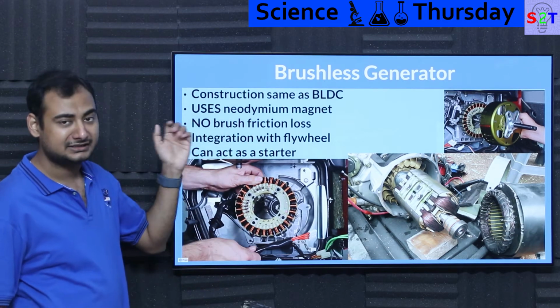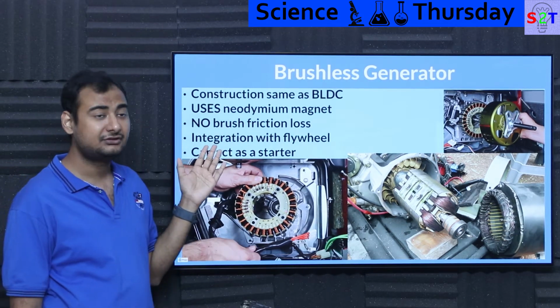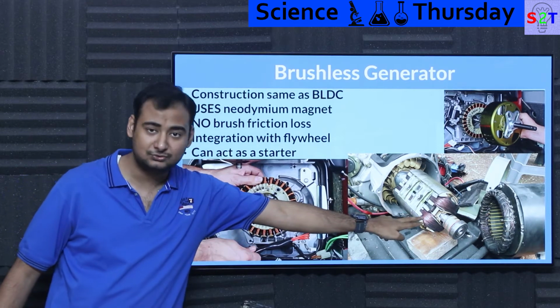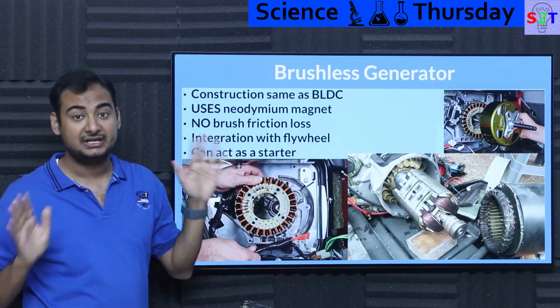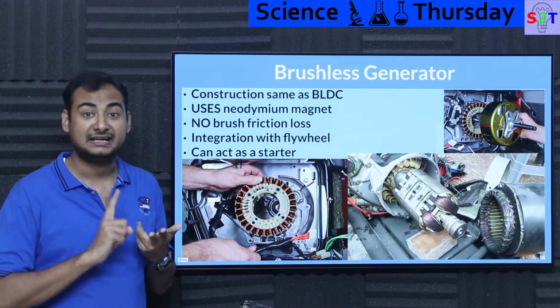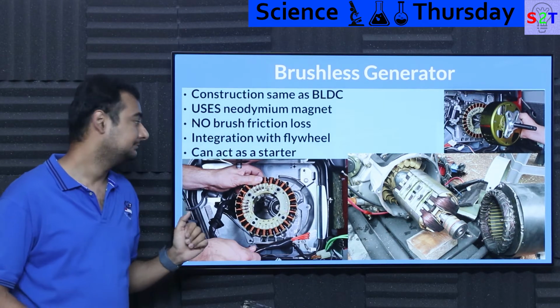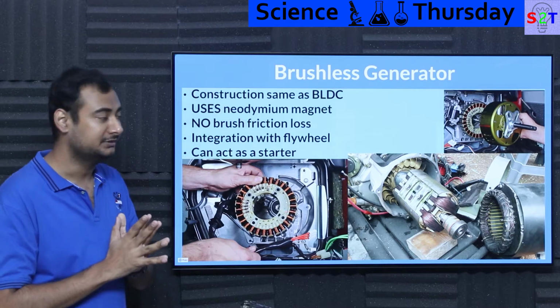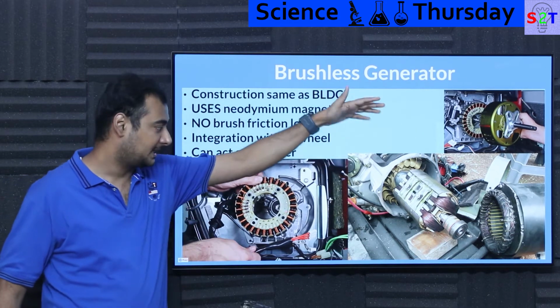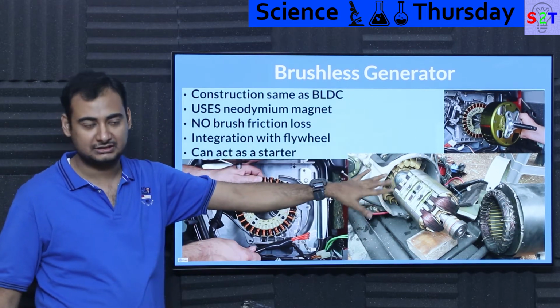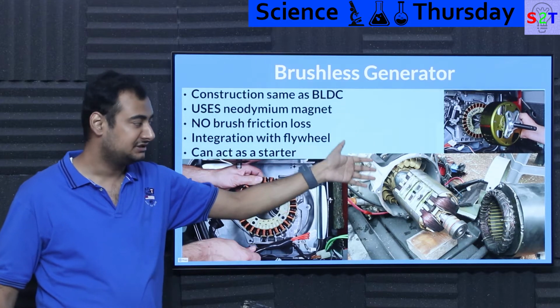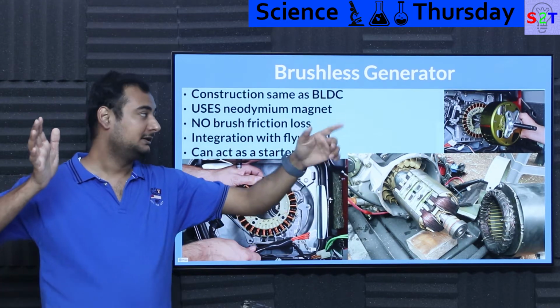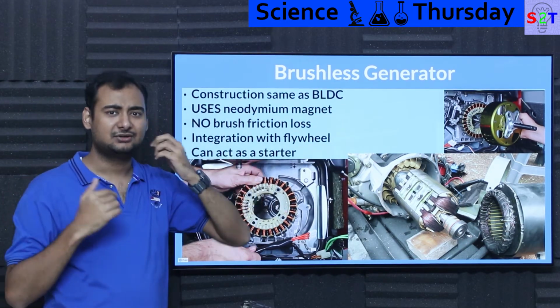So it uses neodymium magnets, and the benefit of that is there are no brushes. You have two brushes here, you don't need any brushes. Fundamentally it reduces friction loss and electrical loss, so that's awesome. And because of the design, because of the compactness of the equipment, this is basically the flywheel. When you are talking about a normal combustion engine and generator unit, it is this big. On this puppy, it's this big. Now you're like, how the heck did it become smaller?